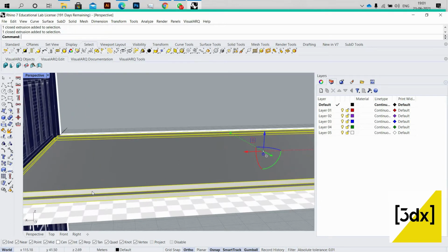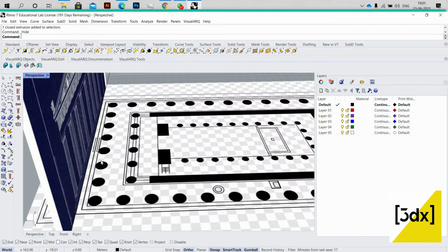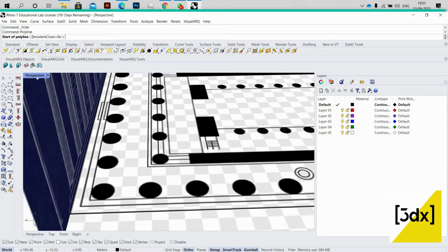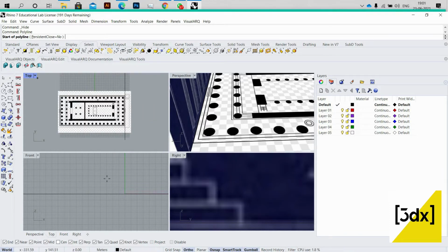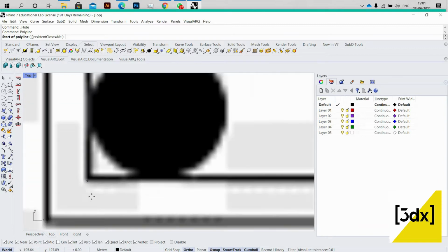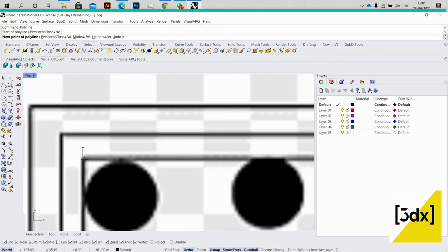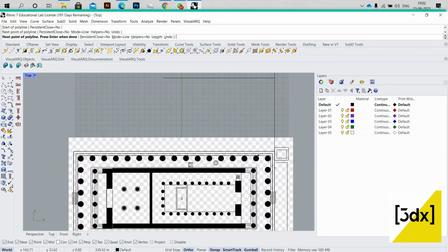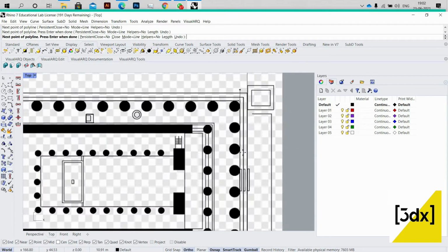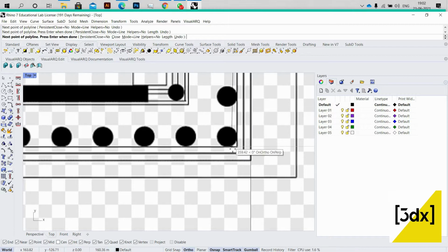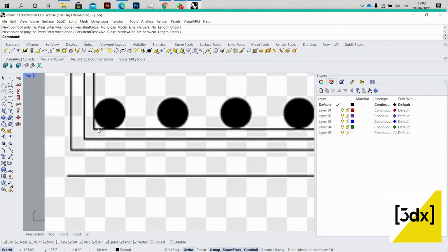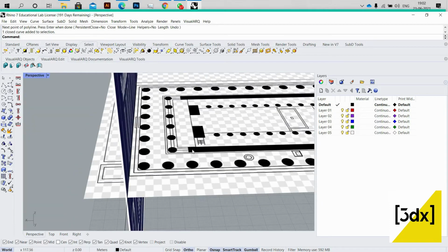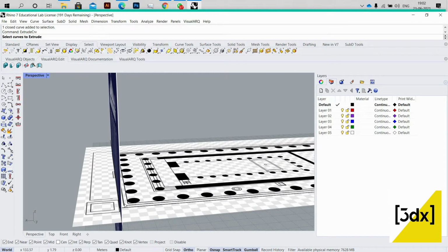Because in the elevation there is a podium called a base platform, which is a kind of steps, I'm creating it with the help of polyline and the extrude command. I'm drawing the third step, that is the third podium level. It has a podium level which consists of 3 steps. So I'm drawing a rectangle with the help of polyline. The rectangle has been done. So I'm using extrude curve again.